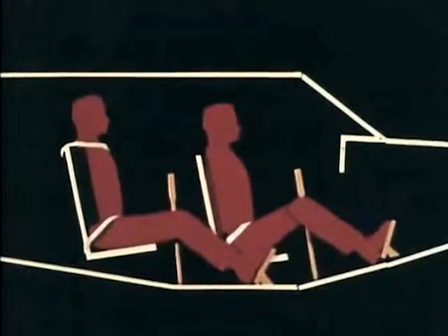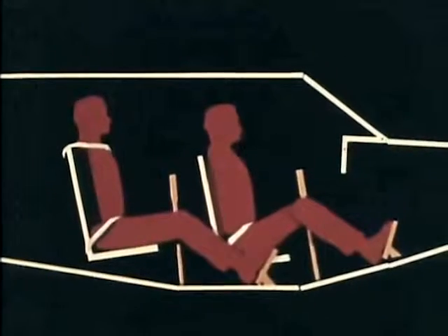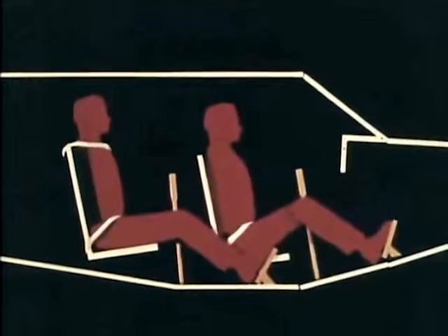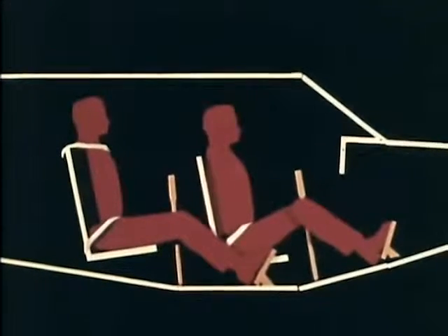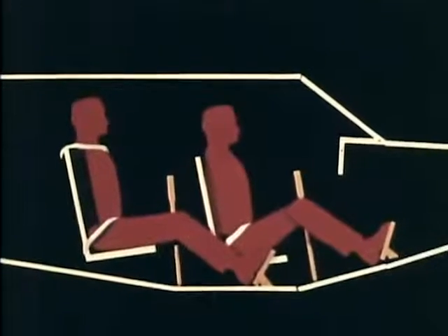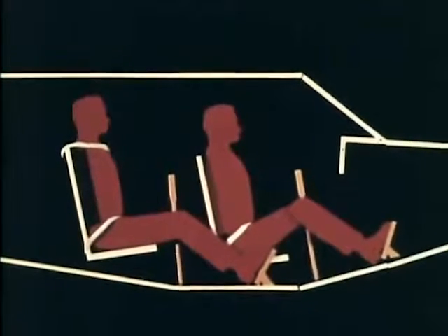The motion pictures obtained verify that most of the injuries that result from light airplane accidents are caused by the occupant striking part of the airplane inside the cockpit. These injuries occur in two ways. When the airplane structure collapses and strikes the occupant. This happens to the occupant in the front seat of this model. The occupant can also be injured when he is improperly restrained and moves from his normal position to strike objects in the cockpit, as illustrated here by the occupant in the rear seat.